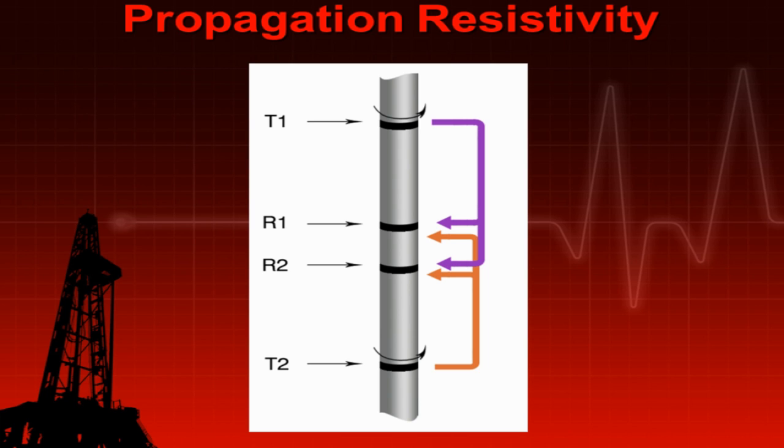And so you're going to make the measurement from this direction, and then you're going to make the measurement from this direction, and we do that to improve the quality of the measurement, to implement what we call borehole compensation. If any of you are familiar with the acoustic sonic logging tool, they use the same approach to compensate for variation in borehole and other environmental effects. So no extra charge for that.